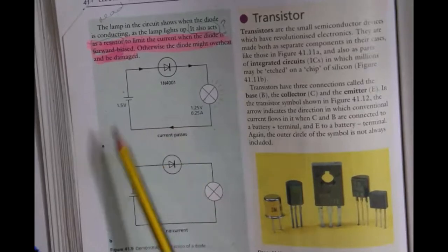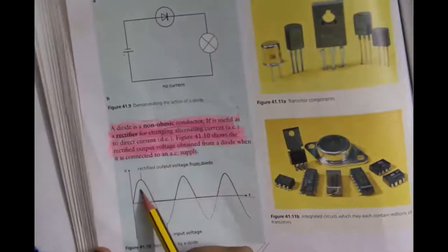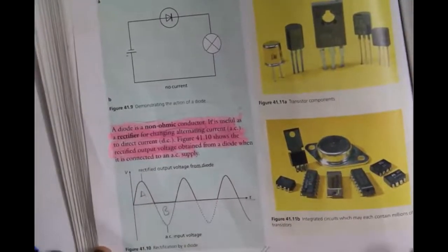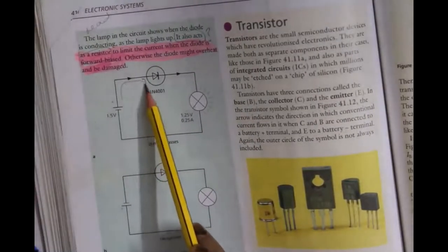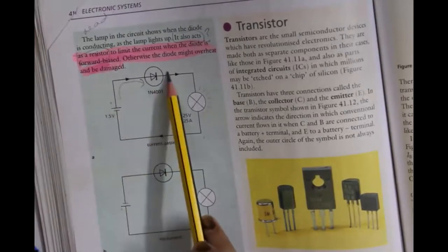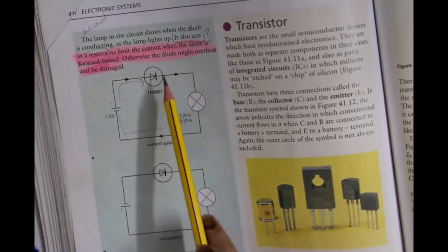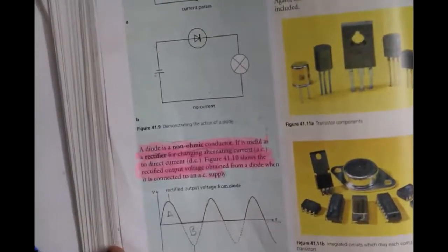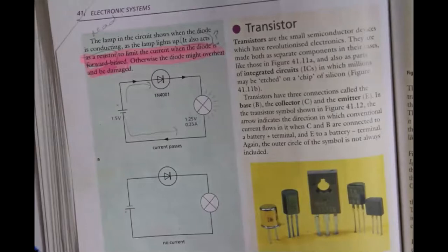Yeah. So, for example, let's talk about instance A and B here. At A, it's going in this direction. So now the diode is fine with this current because it's forward biased. But when it starts going in the opposite direction, this way, it's reverse biased for the current at instance B. So that's what I was saying. Okay. Move on.